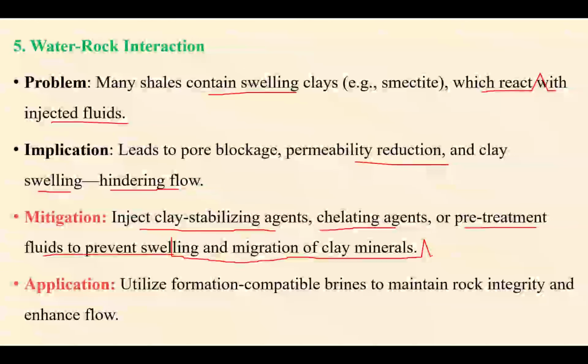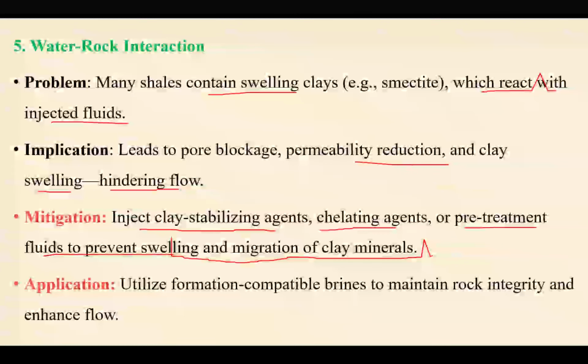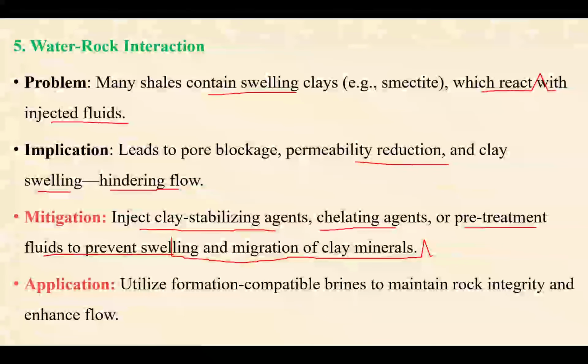Otherwise, as we have already mentioned, the permeability and porosity are very low, and if there is significant swelling of the clay by injection water, that reduces the efficiency of the recovery significantly. So different anti-swelling agents are to be used so that you can get enhanced flow.